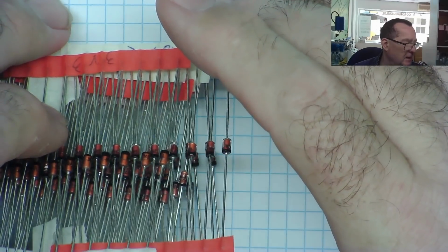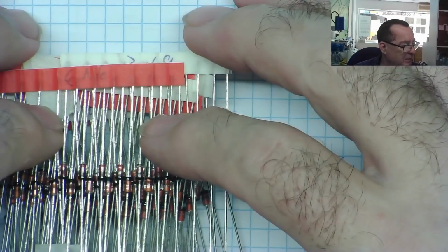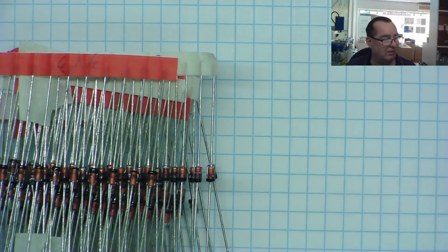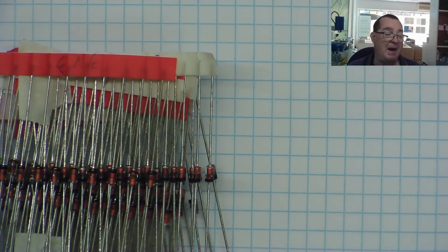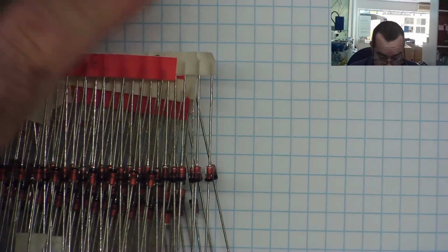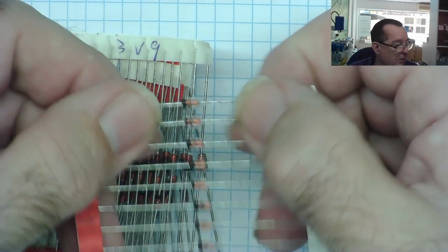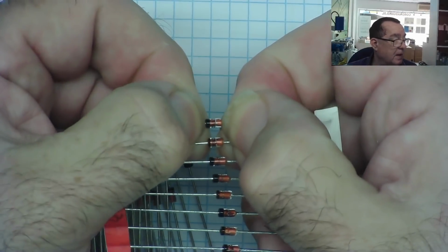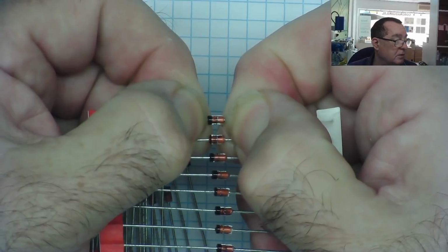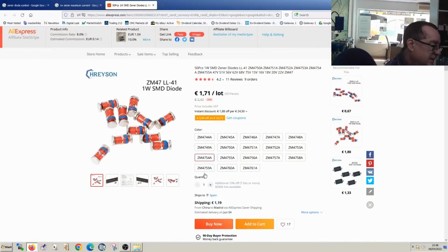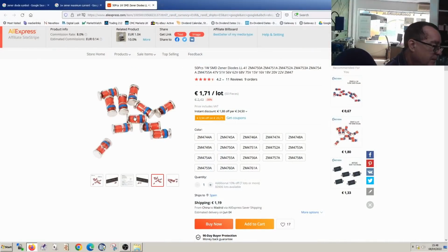You don't really tend to see that very commonly these days, and that's because a Zener diode is quite an inefficient way of regulating the voltage, and for higher powered uses there are far more efficient methods in use these days. Surface mount ones typically look the same as this, but just have metal caps at the end, like between my thumbnails here. So it's just soldered straight down to the board, a couple of metal caps on, and there are no leads. I don't have any to hand, but a surface mount Zener diode looks basically like this.